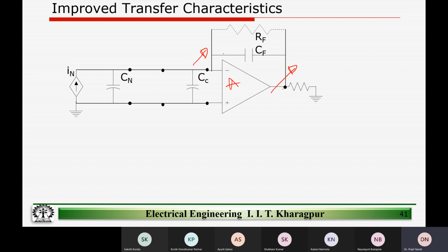Because it's a capacitor. The job of the capacitor is not to let the voltage across the terminals change, right? So if you are pulling one terminal up, the other terminal of the capacitor will try to follow, right? As long as if it's a hard connection, then it can't follow. If it's a ground connection, then it can't follow, right? But here in this case, it is not a hard connection. So it's a feedback. But what kind of feedback? Ayush, any comment? What kind of feedback?